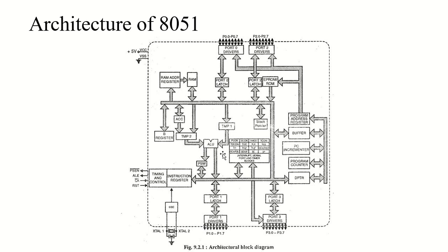Now coming to internal ROM, the 8051 has a separate memory for program and data both, and these memories have the same address ranges. So the internal ROM is used to store the program code, self-explanatory. It occupies the address space ranging from 0 to 0FFFH. Now the program counter can access the program code bytes from 0 to FFFH, and the capacity of internal ROM is from 0000 to 0FFFH.